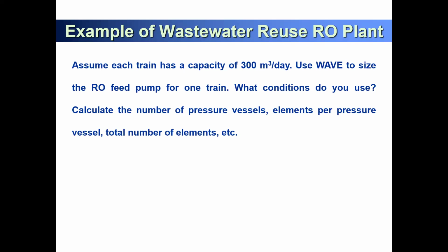Because wastewater contains a lot of organics, also a lot of fouling. So if you increase more than 90%, you completely clog your outer membrane. So for wastewater, we don't really go for very high TDS brine concentration. So go for almost 10 grams per liter of your brine concentration, which means around 80% to 90% of the recovery rate. So we try as an example today for water reuse our plant.